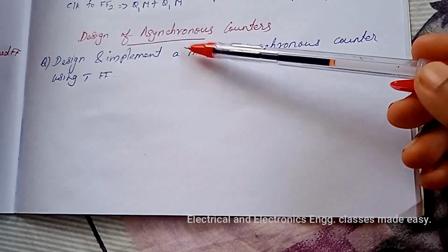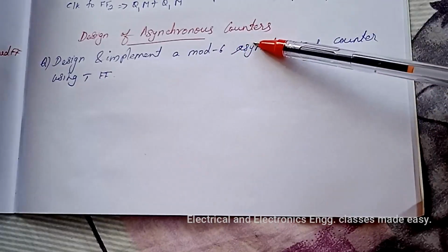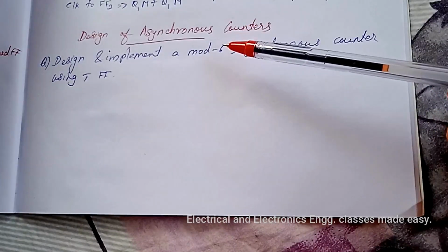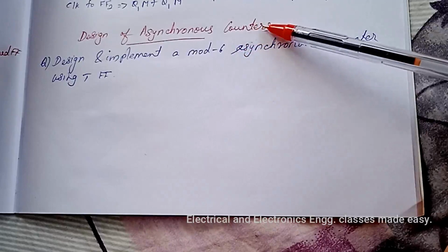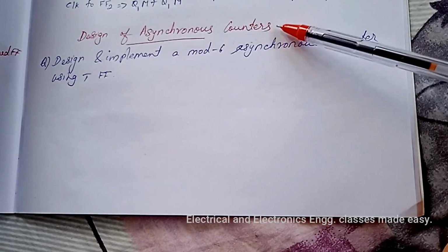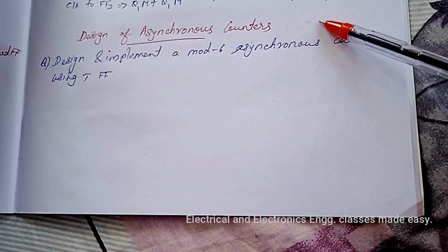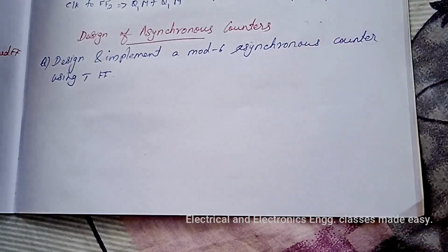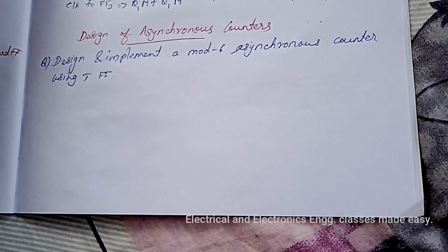Today's class is about design of asynchronous counters. To design an asynchronous counter, first write the counting sequence, then tabulate the values of reset signal R.